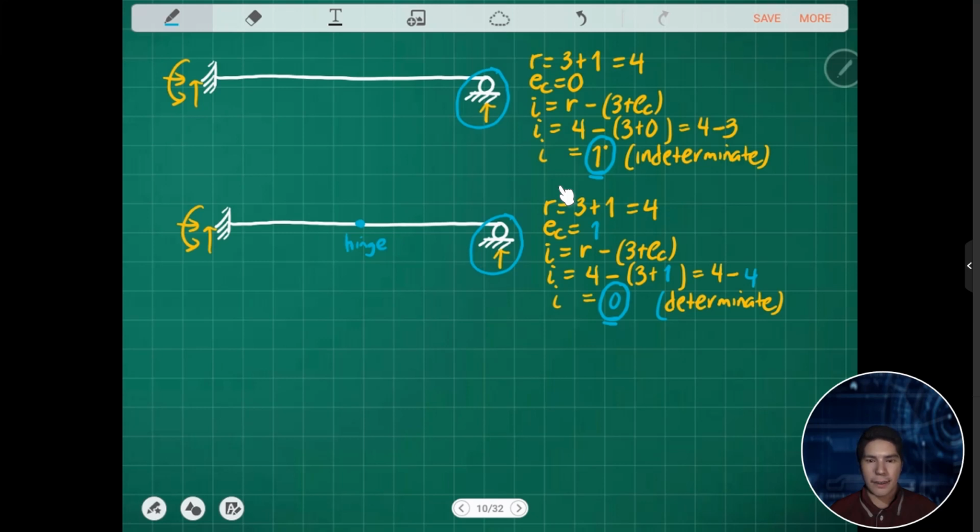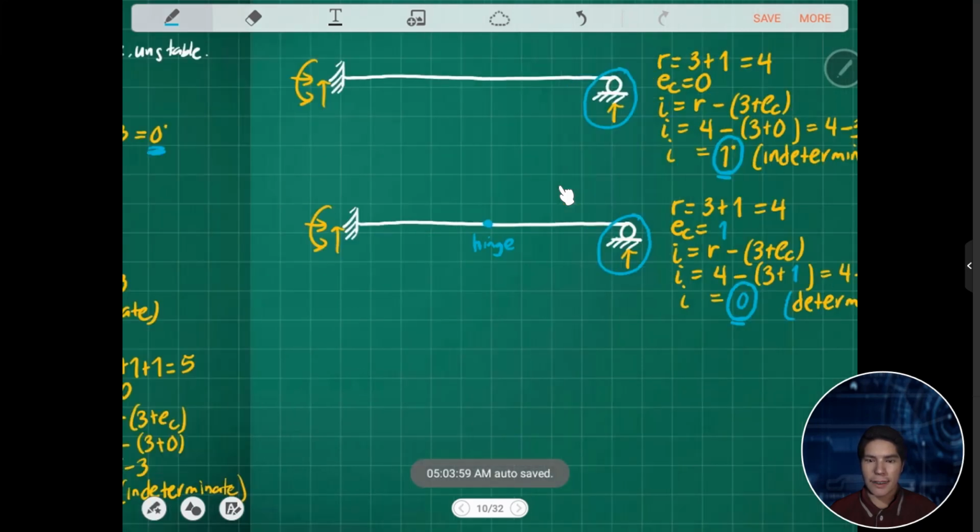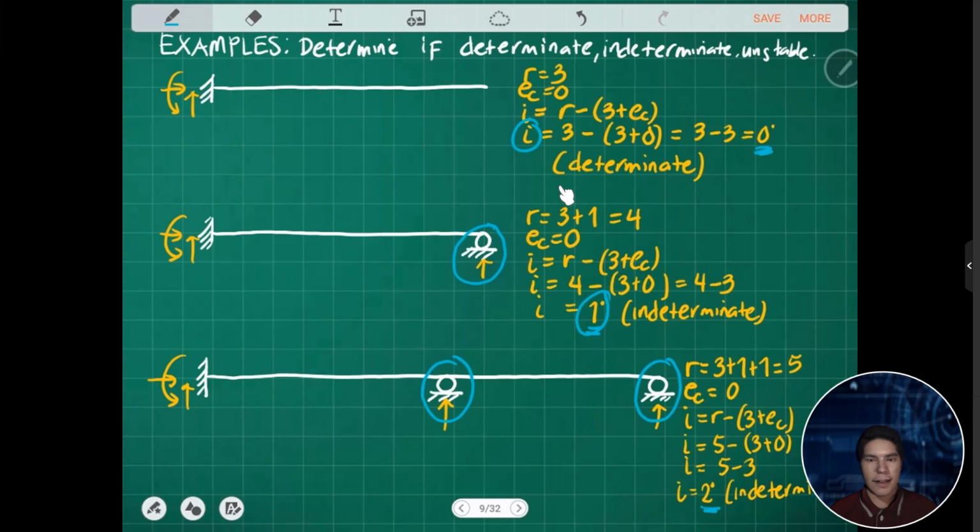If you plot the moment diagram, you can get the elastic curve. The point of inflection is where you can place the internal hinge, since the moment there is 0. So there is a specific position where it should be placed.